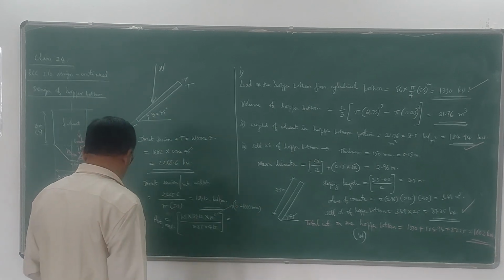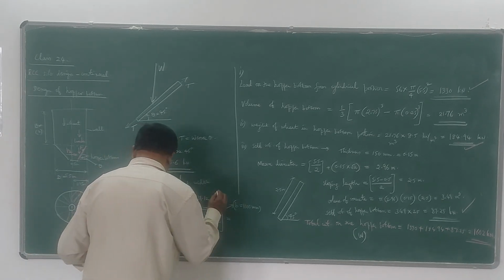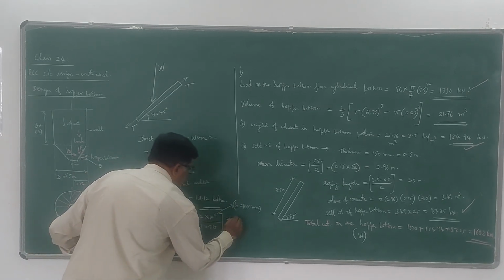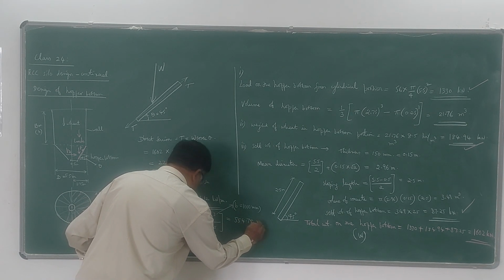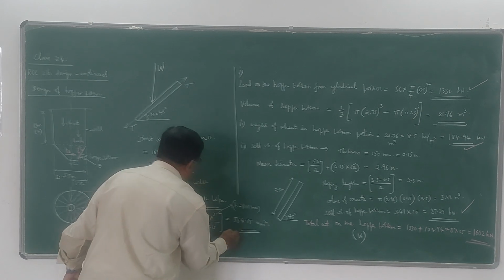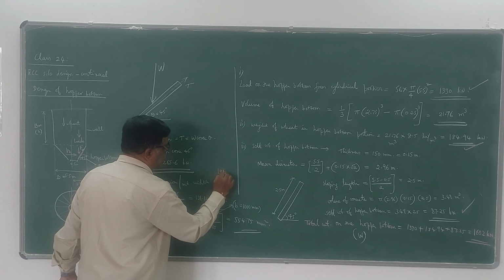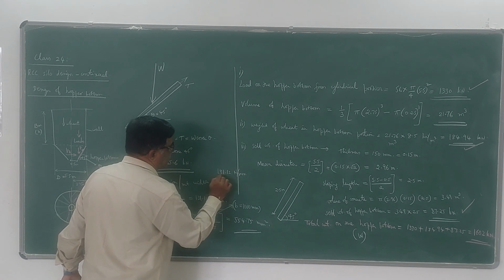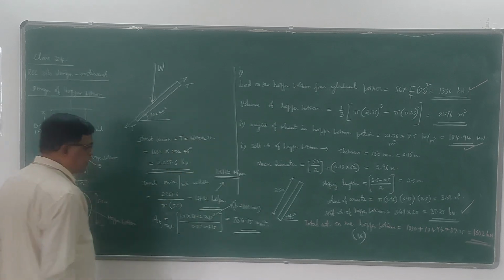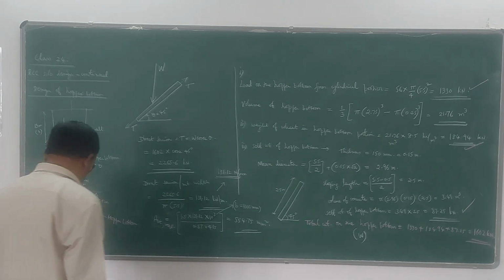So the value you are going to get is 554.75 millimeters square. Here 131.12 kilonewton per meter is the same as 131.12 newton per millimeter, so that's why we take the same value. In the expression for AST required, the value should be in newton and millimeters.